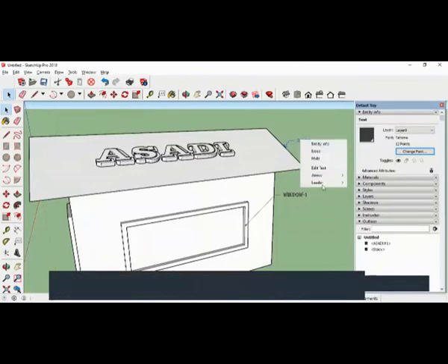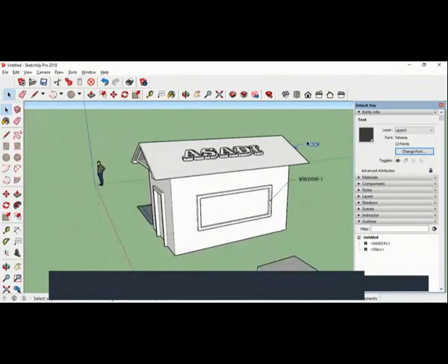If you don't want the leader, hide. So no leader is there, only text is there. Right click, leader, remove the tick mark, leader. Okay, so this is how you do the text. So we have seen the 3D text, 2D text. Now let us see dimension.